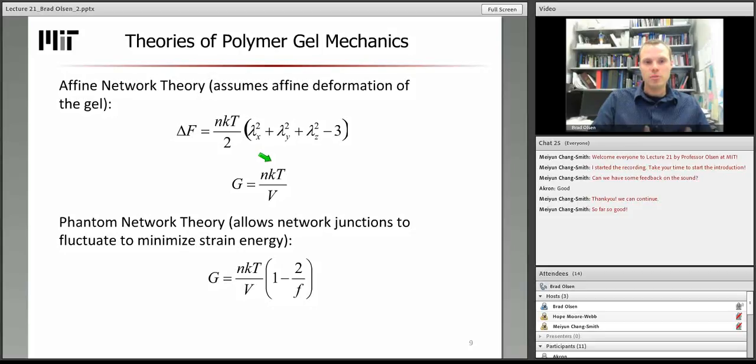I think it's surprising how few variables come into this in a direct sense, because everyone intuitively thinks, well, if I increase the concentration of polymer, won't the stiffness of the network go up? If I change the molar mass, won't the stiffness of the network change? And all this is certainly true. As one increases the concentration of polymer, of course, the density of elastically effective strands goes up, and that makes intuitive sense. As one increases the molar mass of the polymer, remember that the gel is most likely being considered at a fixed concentration of polymer in terms of grams per volume, for example.